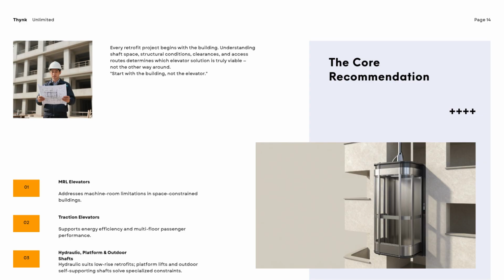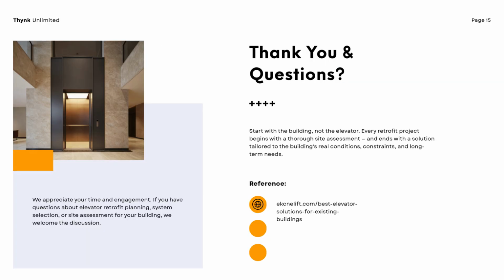The most important principle is simple. Start with the building, not the elevator. Evaluate the available shaft space, pit depth, overhead clearance, structural conditions, traffic requirements, installation access, maintenance access, and long-term operating needs first. Then choose the elevator system that fits those conditions.